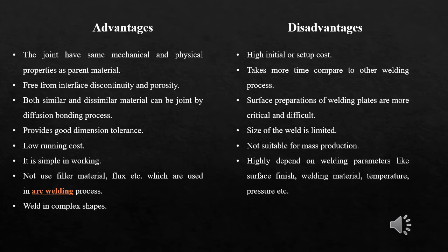The disadvantages are high initial cost, it takes more time than other welding processes, surface preparation of welding plates is more critical and difficult, the size of the weld is limited, it is not suitable for mass production, and it is highly dependent on welding parameters like surface finish, welding materials, temperature, and pressure.